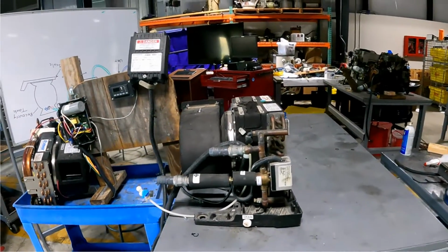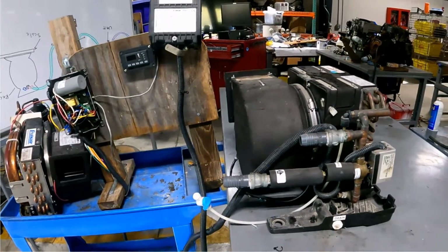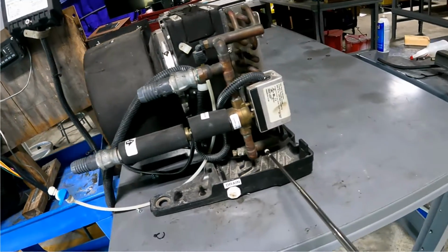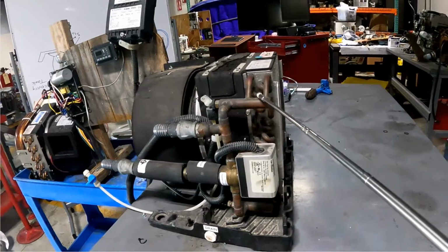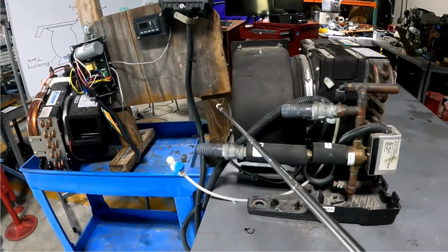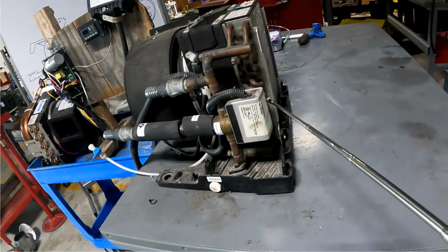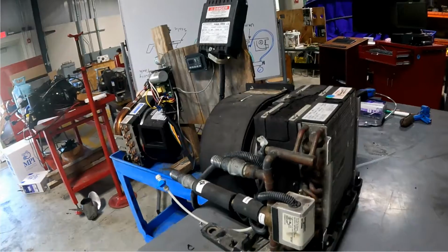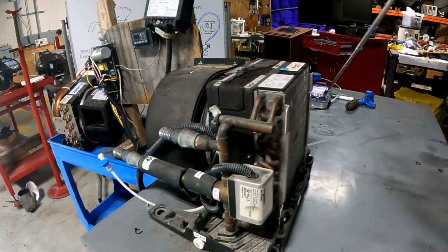In this example, we have an air handle. This is the air handle. This is the flow of fresh water. The fresh water enters over there, enters in the bottom, circulates through the coil, and returns. And this is the return of fresh water. That's the input, pass through the coil, and return over there. The air filter is located here, over there.